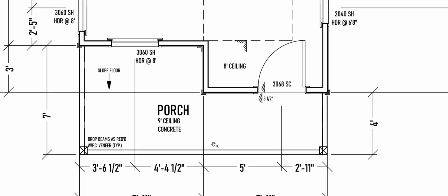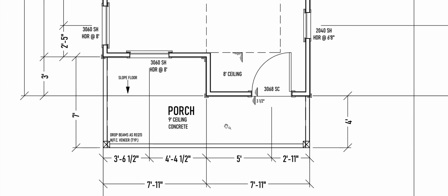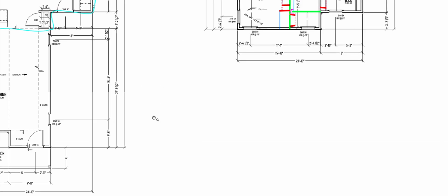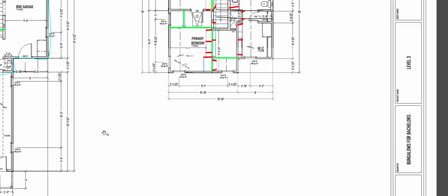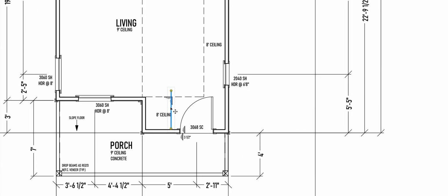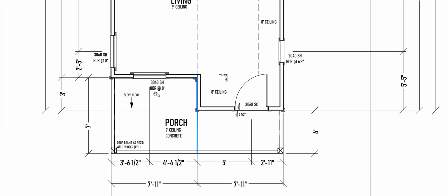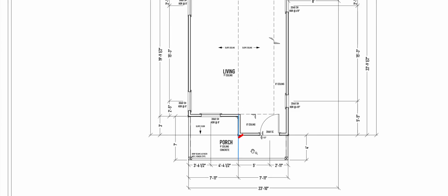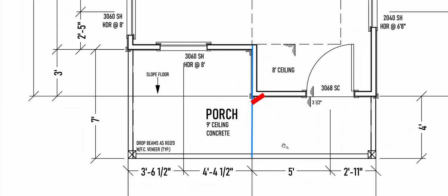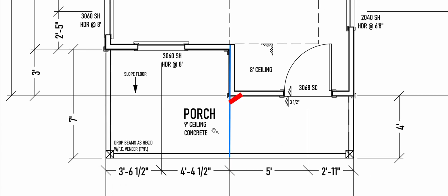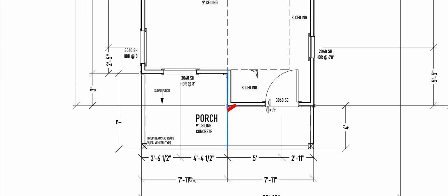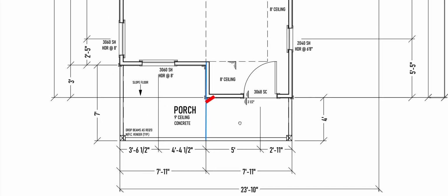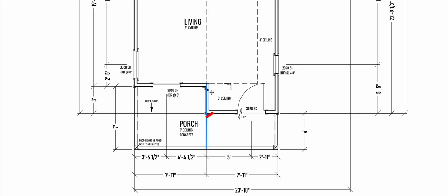This porch is a flat ceiling and it's a steep roof. So whatever little ridge, actually I'm going to copy. Whatever little ridge exists right here to here, I can just brace down onto this wall. All right, so that ridge is braced to here, and this is a super short span for my 2x6s. There's no special geometry here. I'm starting at the wall and I'm going to here, and that spans 7'11". I know I can go 11 feet with that 2x6 24-inch on center rafter. So I'm going to do that. Okay. So that takes care of the front porch.